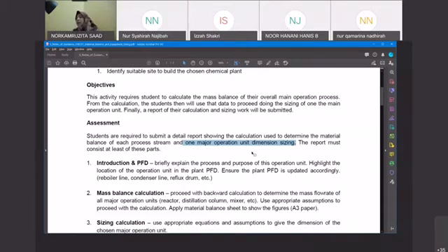So maybe the contact between the liquid and the gas plays an important role. So you would like it to have more contact in that particular column. Therefore, you introduce the recycle stream so that most of the product that you're going to recover will be recycled back in the column, okay? Or you can have a reflux. So that is another design if you're talking about distillation, okay?